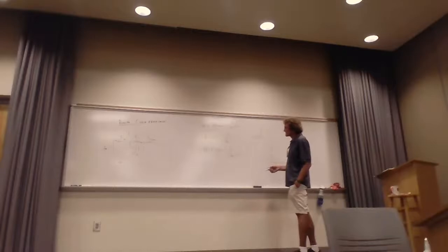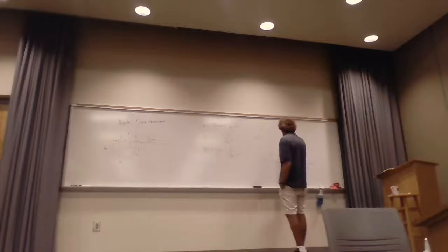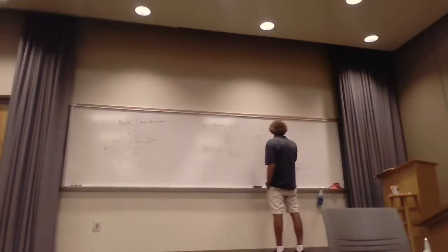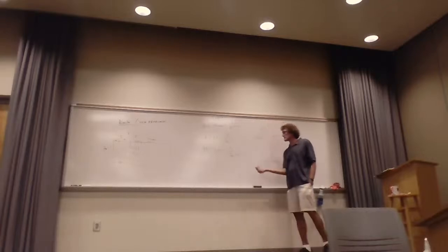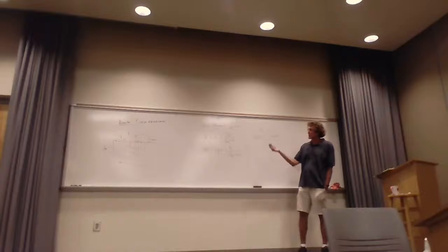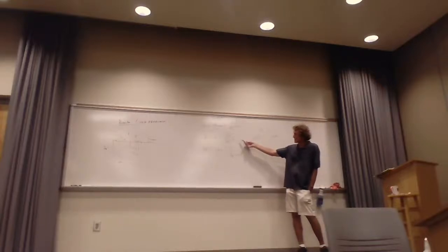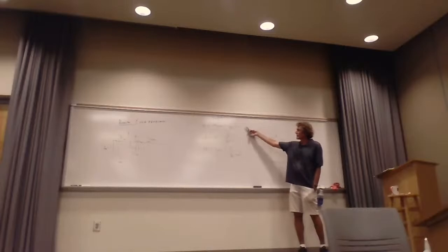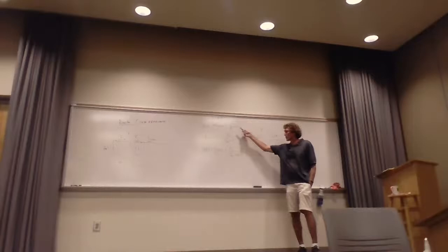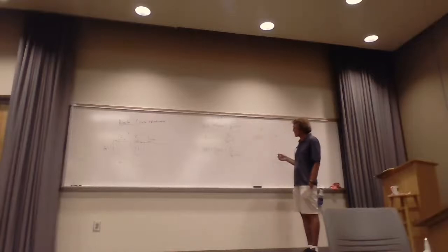At very low frequencies, when omega is 0, it's just R. So normally what they'll do is show this come in as just the log of the magnitude of R. I know that because if I look at that, as s goes to 0, I get 1 over (1/R plus 0), or just R. It starts off there.